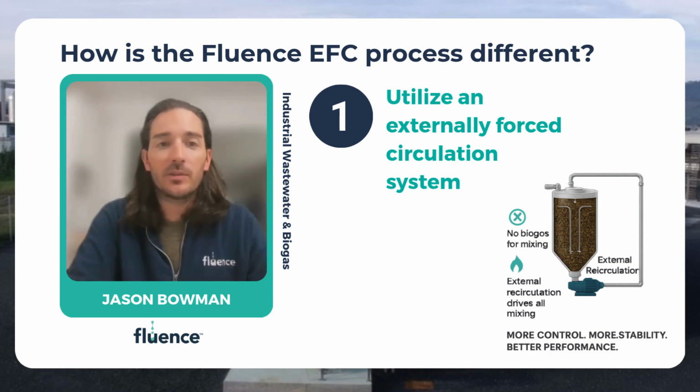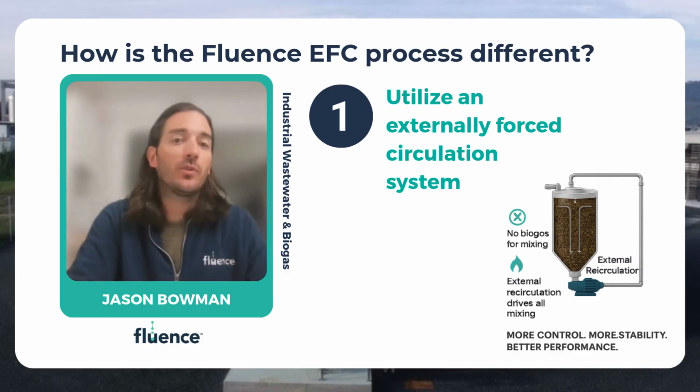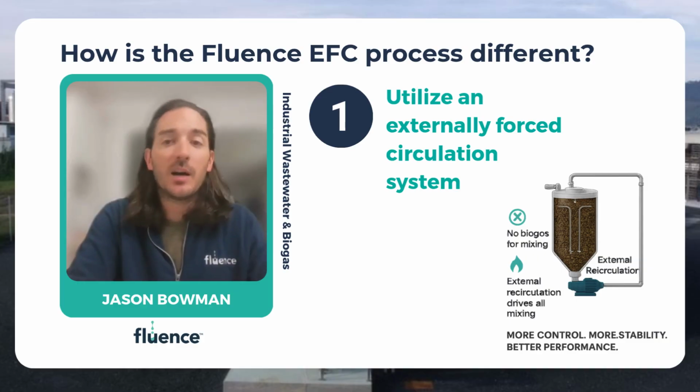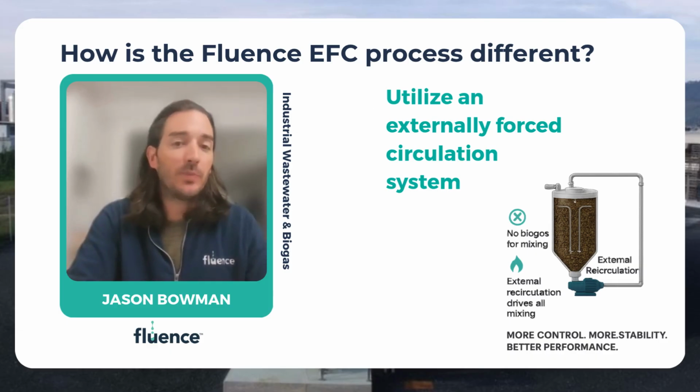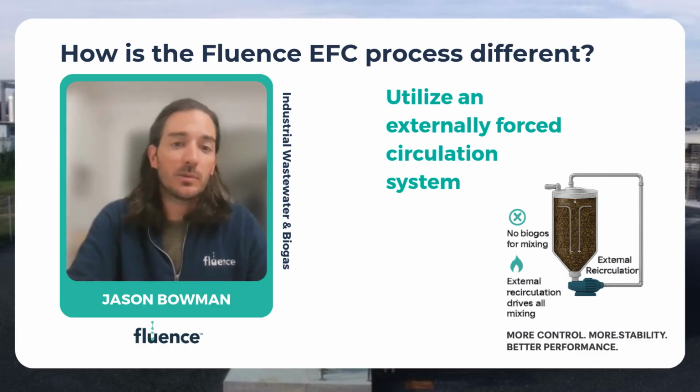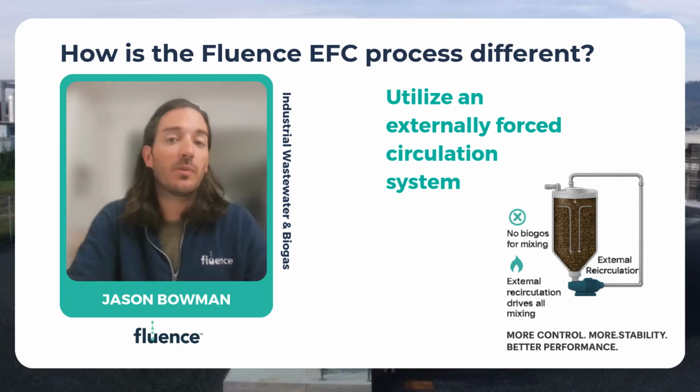So without consistent external mixing, it can lead to stratification within the reactor during periods of low biogas production and lower mixing. By contrast, an external mix process that relies on controllable liquid mixing delivers a more consistent, more controllable reactor velocity, granular velocity, independent of the biogas output. So this results in a more predictable, more controllable, and more stable operation for these systems.